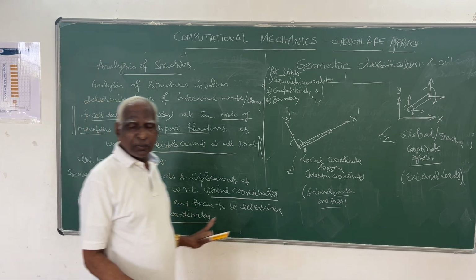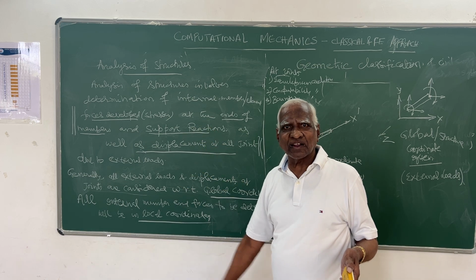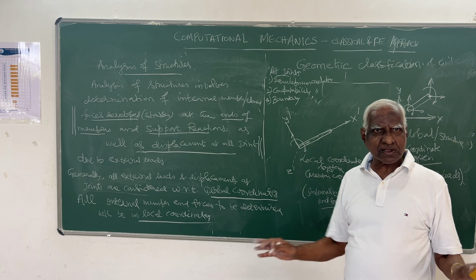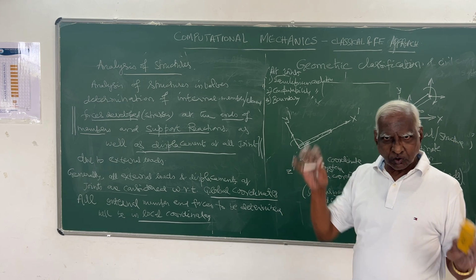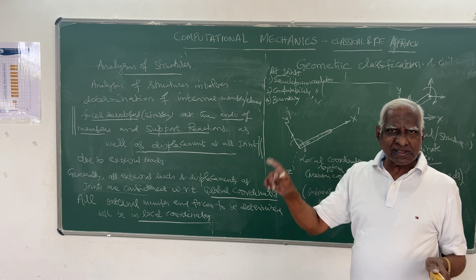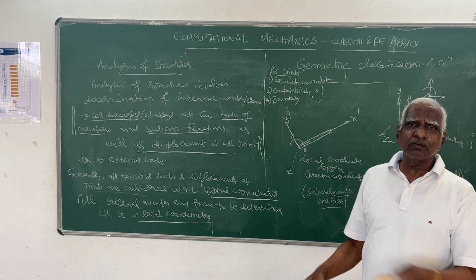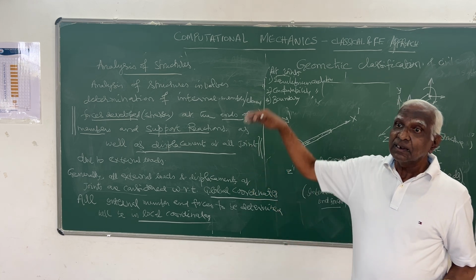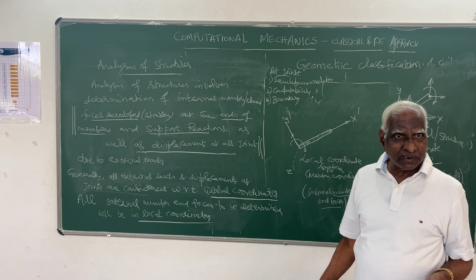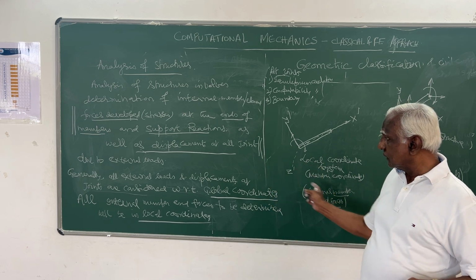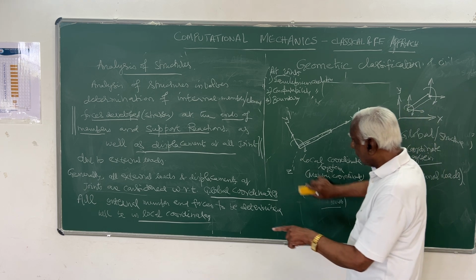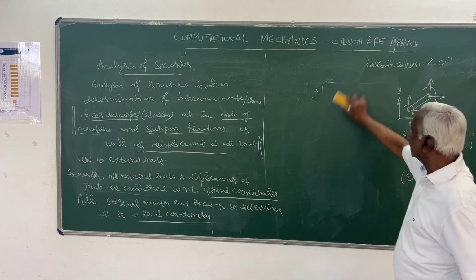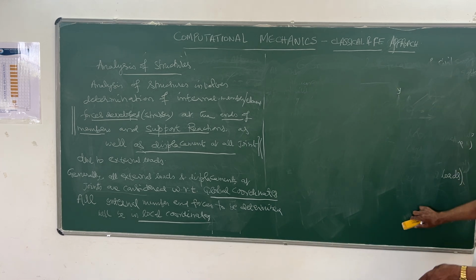So this is a very, very important aspect in this matrix method of analysis, compared to the classical method, because hitherto we talked only about forces and corresponding displacements. So external loads and internal forces developed: the external forces are with respect to global, and the displacements again have to be with respect to this.